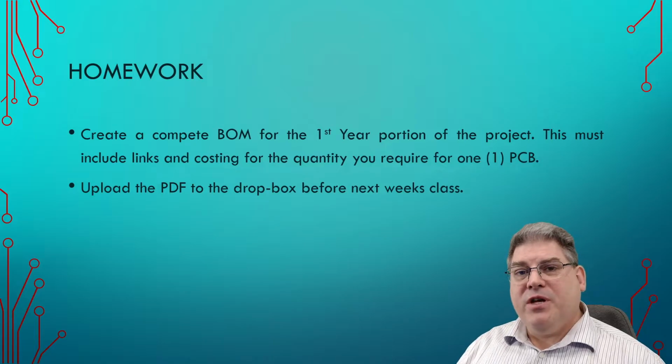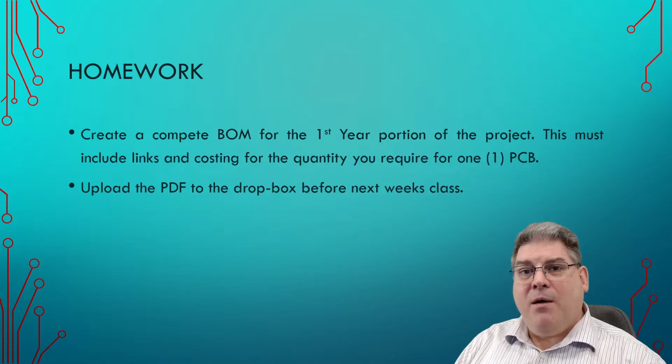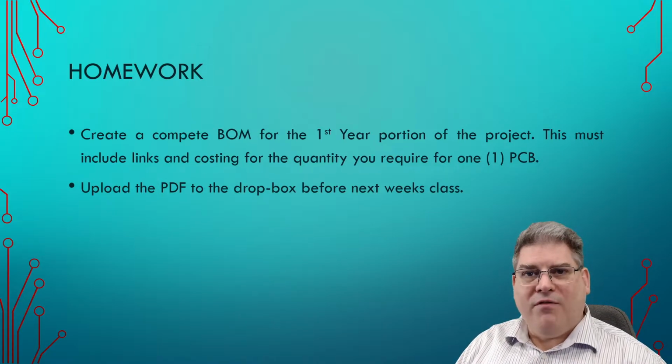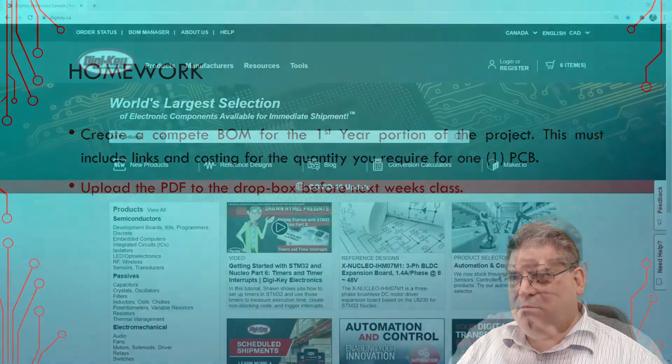Make sure that you do look at the MOQ, so the minimum ordering quantity. Make sure that you look at the stock available, and do keep an eye on the footprint and the costs.